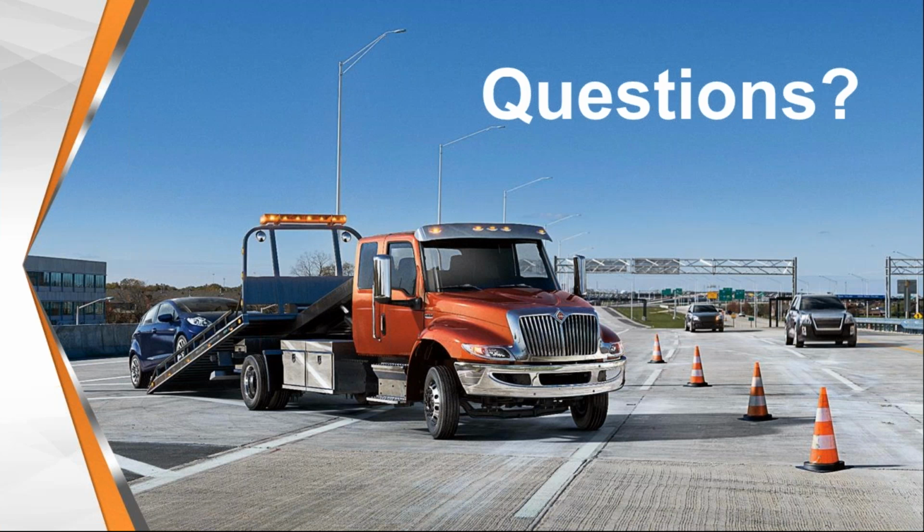Our software has the capability of looking at inputs, looking at outputs, and what we can actually do with our software is override or simulate an input. We can override and simulate or force an output. What we don't see, what's in between there that's separate from ins and outs, are the algorithms or the software inside, all the little things that have to be met as far as pressures and temperatures before an AC clutch will engage. Those are not seen, but you'll have to go into your diagnostic manual to actually see those criteria.